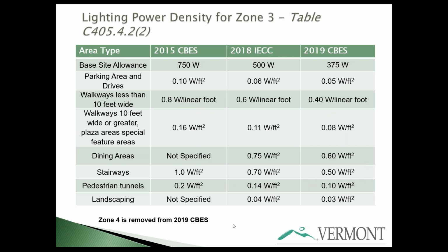Now we're going to get into exterior lighting. Oh, one thing I forgot to point out when we were covering the interior lighting is some of the stakeholders had concerns about areas where there are elderly people in them. We do, in the space-by-space lighting power densities, allow for more lighting power in areas that serve the elderly. But if you're to take advantage of that, you need to do the space-by-space method, and you will find more lenient code requirements in those cases.